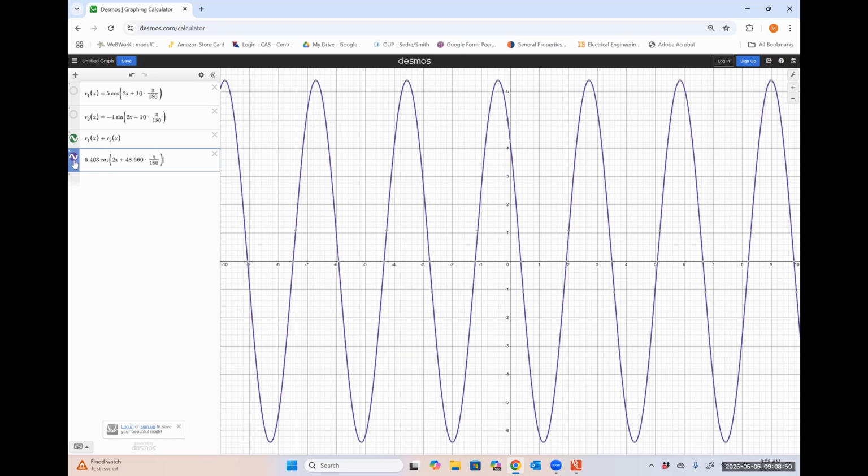Yes, sir. So if that 2t was different, it breaks the third rule that we established earlier. It's impossible for the 2t to be different in a circuit like this. What I mean by that specifically is if I sinusoidally excite a system at one particular angular frequency, all of my responses will have that exact same angular frequency once I hit steady state. So we just used complex numbers to legit avoid 20+ minutes of trig.